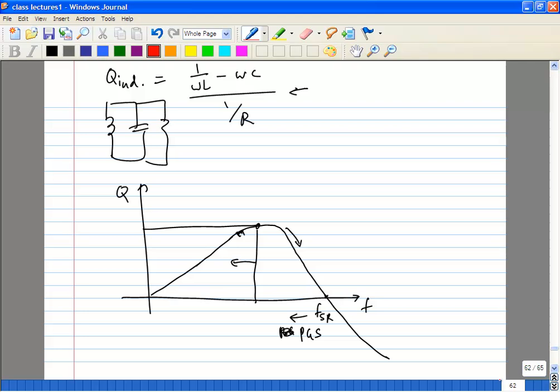Earlier, when people used to work with discrete components, the distances and other things were large enough such that they were comparable to the wavelength, maybe several orders higher than the wavelength of the signals you work with. Whereas now we have reached a point where on an IC, the connection between, let's say, a transistor and this inductor, or the next amplifier stage, is much shorter than the wavelength of the signal you're working with. So that means you don't have to consider distributed effects.